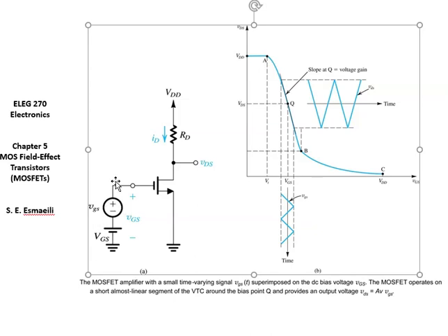So what we want to do is amplify this voltage here by the use of this MOSFET in the saturation mode. And what I was telling you before, you can see it here. A small change in VGS can result in a big change in VDS. So you can see the amplification in this graph. So how to do that?